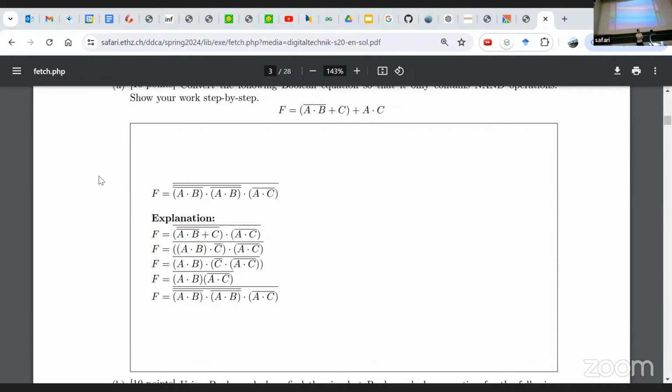And now it's an implementation question. What is easier? To hold part of the pipeline by doing what I said, or by inserting a bubble, letting the pipeline run but inserting in between an operation, so that there's a separation between the leading instruction and the following trailing instruction. Because what you want to do is separate them a little bit.